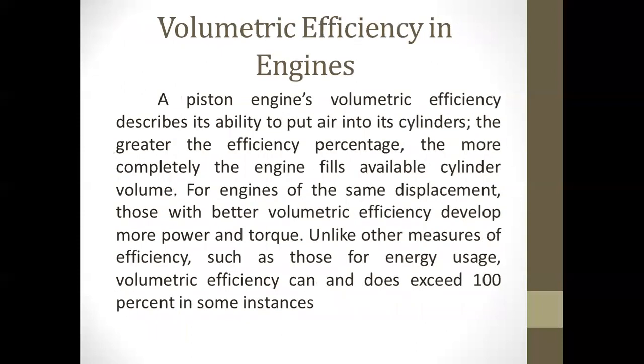Volumetric efficiency in engines. A piston engine's volumetric efficiency describes its ability to put air into its cylinders. The greater the efficiency percentage, the more completely the engine fills available cylinder volume. For engines of the same displacement, those with better volumetric efficiency develop more power and torque. Unlike other measures of efficiency, such as those per energy usage, volumetric efficiency can and does exceed 100% in some instances.